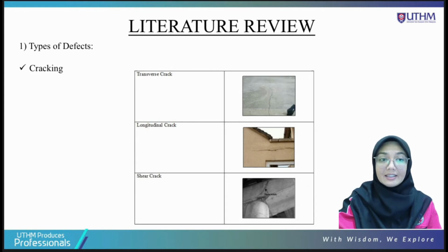Transverse cracks form after hardening. They can be caused by excessive loading from structural, thermal or conditional shrinking of the concrete. For the longitudinal crack, the reinforcement bars are directly affected. Rusting of the reinforcing bars will lead to cracks, which will eventually lead to spalling and the cover's disappearance.